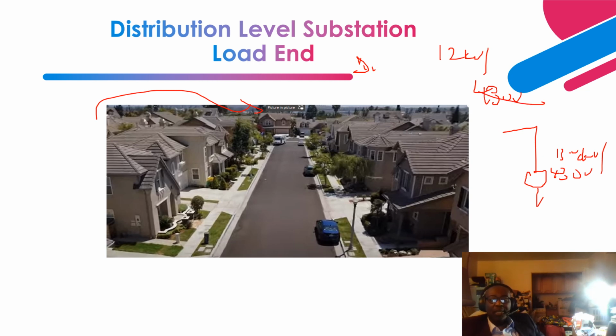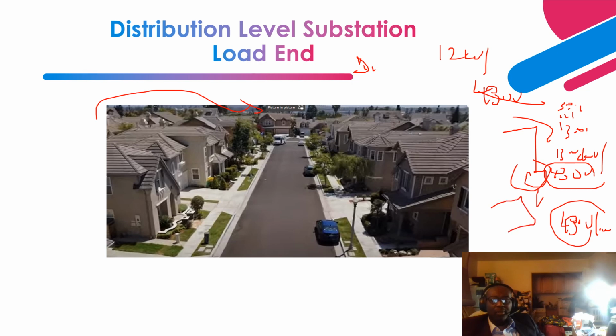So you're coming in at 13.8 kV or 12 kV or 38 kV, or whatever voltage you have, and it steps down to 480 volts. Then it comes to your household. Sometimes you can have other transformers that step it down from 480 volts to 120 volts, and those transformers are either pole mounted or located on a platform on a foundation in your neighborhood.